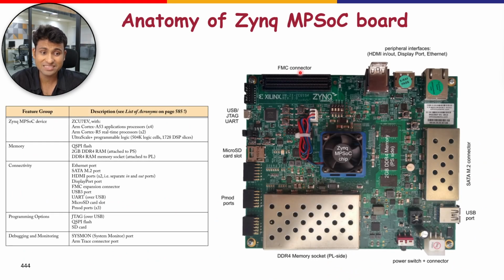At the very highest level of abstraction, a Zynq MPSoC system consists broadly of three elements: the board on which the Zynq MPSoC device sits, then the Zynq MPSoC hardware design which goes into the PL, and the software layers that run on top of the hardware. And of course, this FPGA, through this breakout board, interacts with other peripherals via the interfaces which we have discussed. In the lab sessions particularly, we will discuss the development boards which are commercially available from Xilinx. The typical prototyping board gives us a set of standard facilities and peripheral interfaces which you can see here.